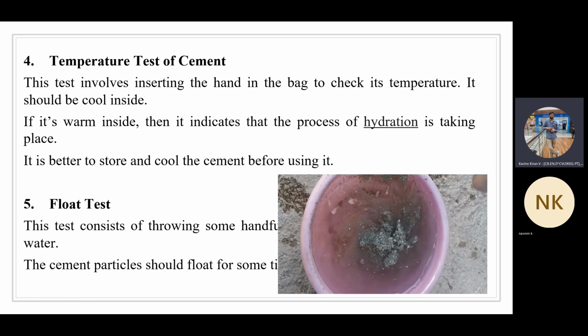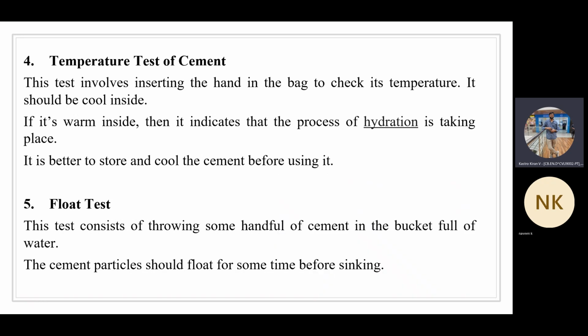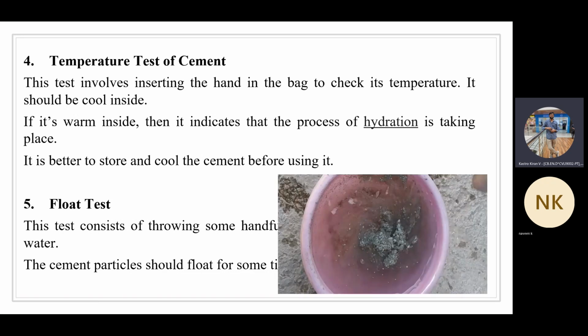Now what happens as soon as you throw the cement into the bucket? What it should feel like is the cement particles should float for some time before they sink. Immediately they should not sink. As soon as you throw the sample of cement into the bucket full of water, first they should float for some time.